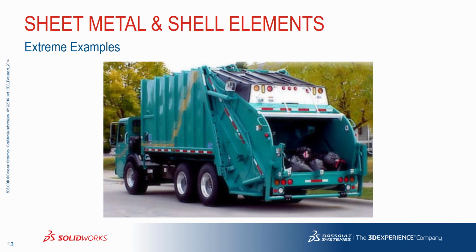Think about this, a garbage truck. The larger your analysis, the more you must be proficient and expert with shell meshing. And to do that, you got to be good with surfaces. So you could, again, model this thing with solid, sure, but if you just tried to mesh and run this as a solid, even the best engineering workstation, it would probably mesh fail. And even if you got a mesh to go on this thing, you never have two elements across the thickness. So a shell version of this, it might take an hour, 2 hours to start setting up the body, but then it's going to be solving in minutes.